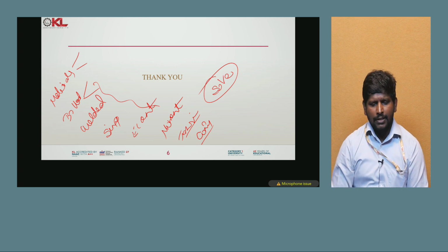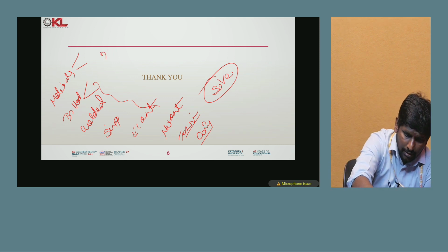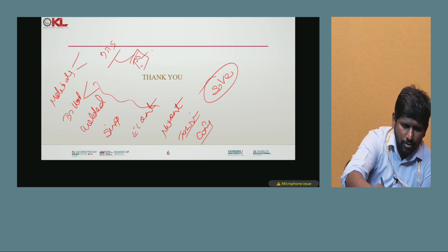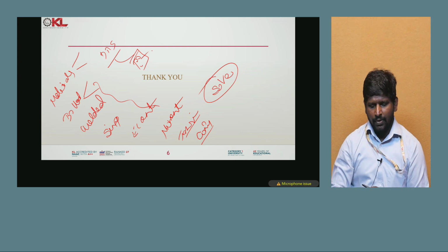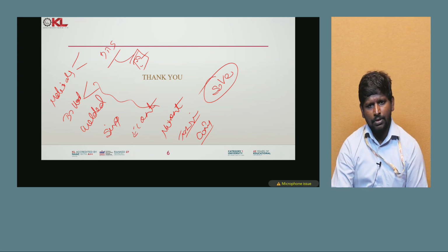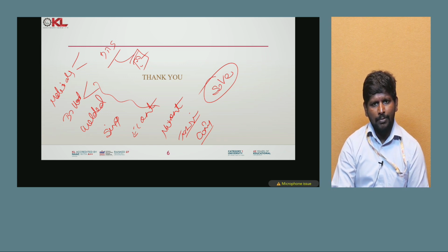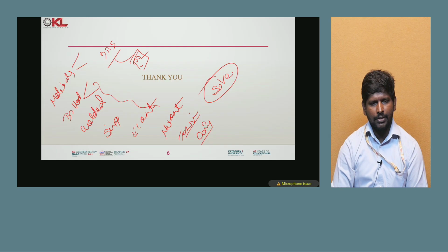It is not like RCC design, which is detailed from step 1 until step 10, finding out the reinforcement details, four bars and like that. No, here it will be like finding out the shear of the bolt, the strength of the bolt, the strength of the plate, everything, and checking the combination of torsion and shear. That's it. It will be complete in a very easy manner. The only thing is understanding the concept with the different variations of materials, bolted, welded, and everything.